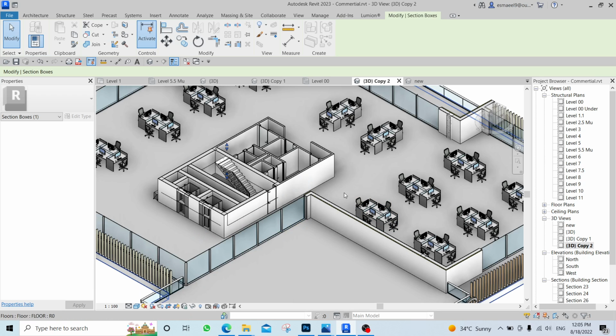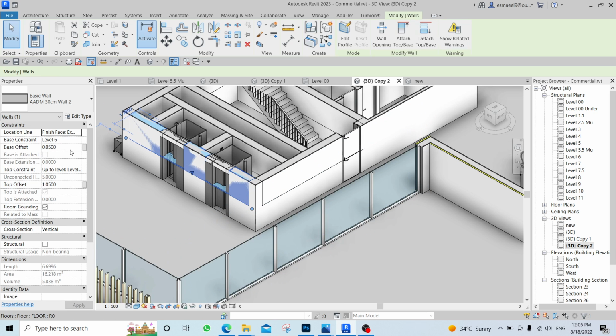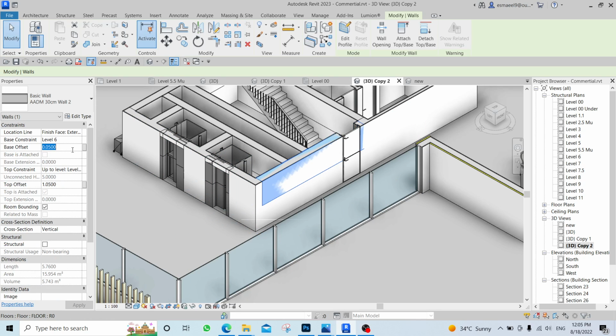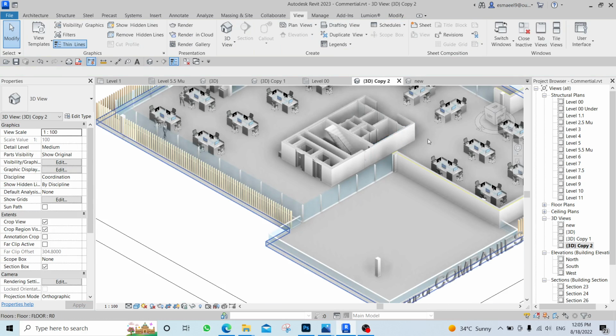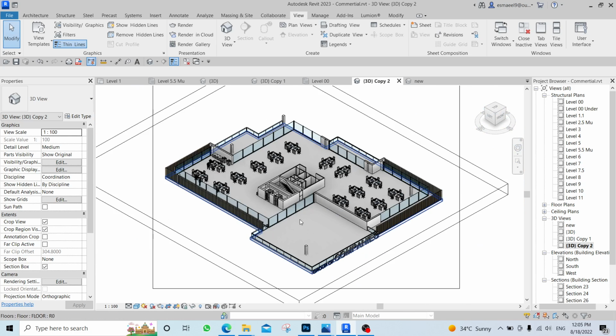Yep. Maybe you will see some problems when you are working. Let me see. This is the base offset. Okay, drag it up. You will see little problems. Let me just put it at 1.5 in order not to see it, because it's a wall which has a little base offset. I will just increase it in order not to see it, and that's it. Yeah. Since I did this, I will just go back to my view, and then yeah, delete this door. It's an additional one.